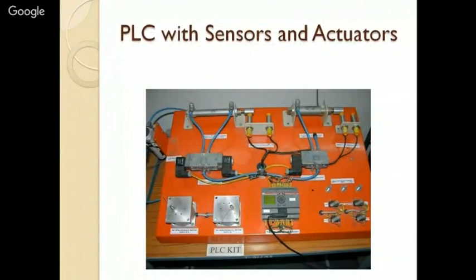Now we'll go on. If we again go back to our overall board of the PLC, here all the sensors 1, 2, 3, 4, 5, 6, 7, 8, 9, 10, 11, all the 11 sensors are digital sensors. The difference is that these 4 are capacitive type proximity sensors, the kind of one you saw just now in the demonstration. These 4 are inductive type. So that means they will detect only metallic objects, whereas these will detect anything which can provide changes to the electrostatic field.